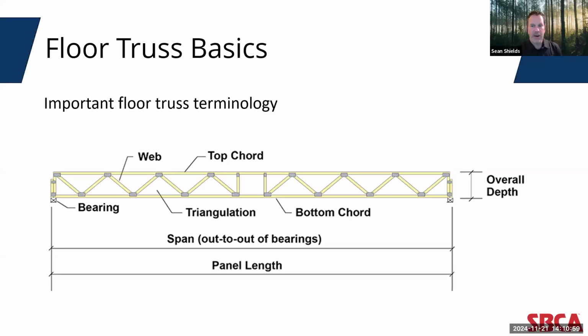The bottom chord typically carries combined tension and bending stresses. Another floor truss configuration is considered top chord bearing. In this configuration, the top chord of the truss is responsible for transferring forces to the bearings. The top chord then carries the combined tension and bending stresses.